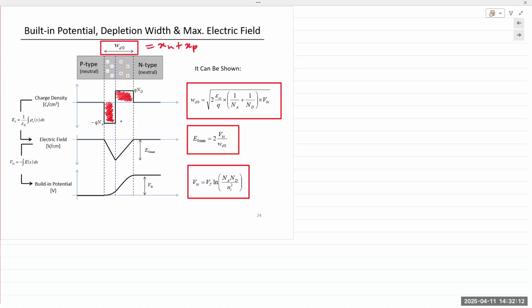And integrate that electric field, and you can express that in terms of a junction voltage. This voltage is not created, but this voltage, or approximate value of this electric field, is built in, it's created inherently. Hence it is known as the built-in junction potential, built-in voltage, VBI.